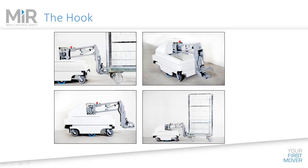At that point, there's a second actuator right here in this area that forces this bar against the hook underneath to clamp onto that particular cart. And once it's got a cart in its grasp, there's another actuator system that's a ball screw right in this area here that allows 2 plates to separate. That is the locking mechanism, or brake as they call it, to hold the hook in place.